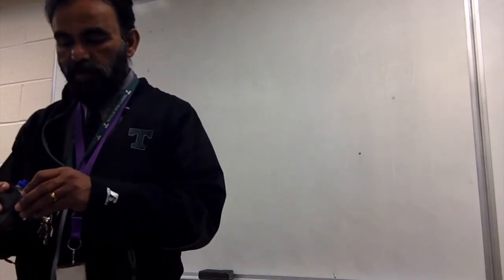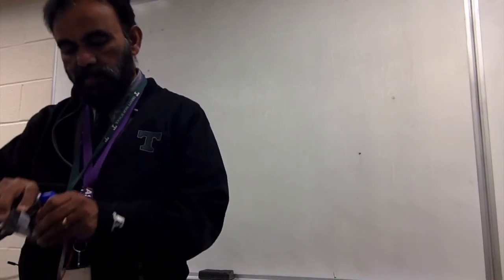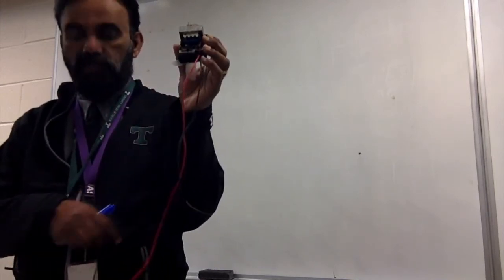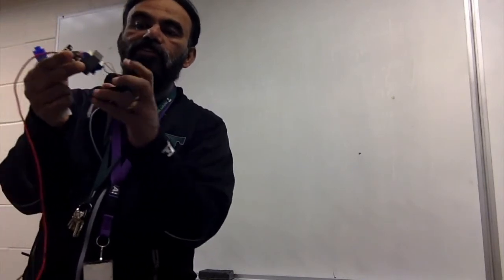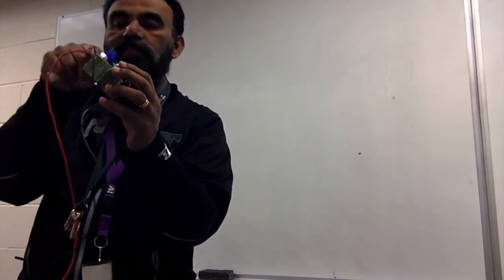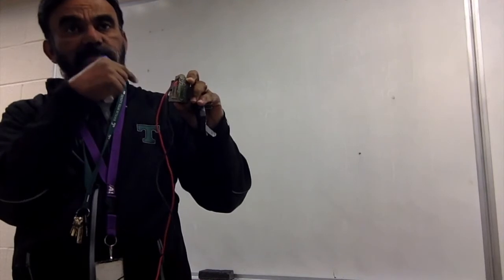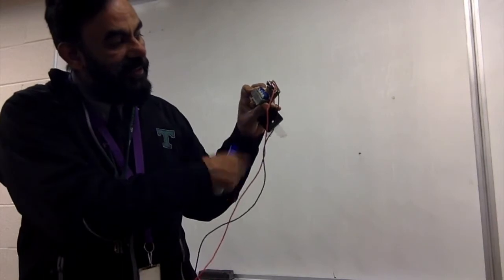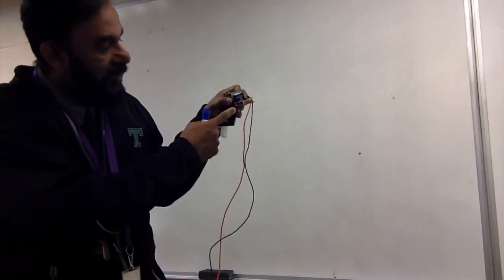Transformers can be used to step up or step down. So in this adapter, the main component of this adapter is a transformer. You see that? That is a transformer. So you can see the 120 is going straight into this transformer, and then the output that comes out from here is passing through some diodes, and I'll explain all that right now. And you can see the main component sitting here. See this? What is that cylinder? That is a capacitor. This one.